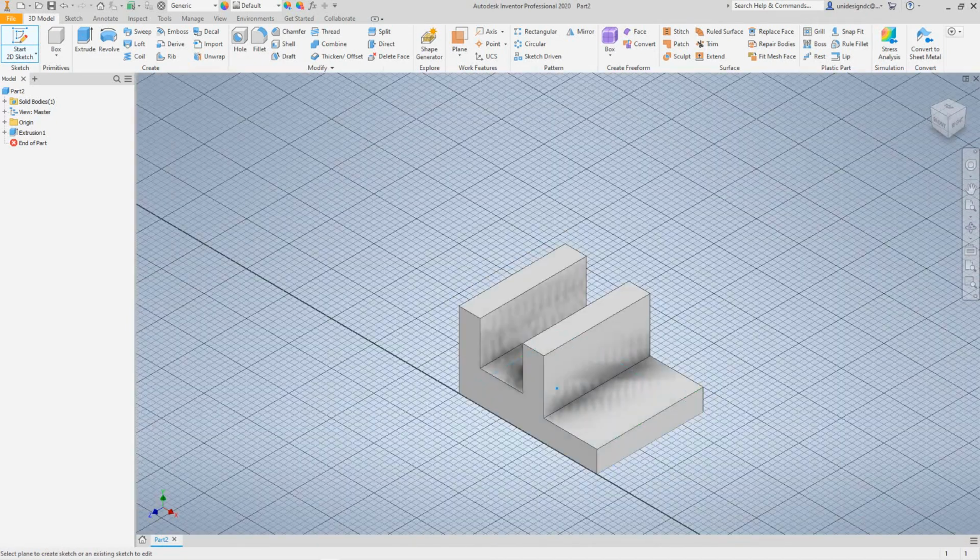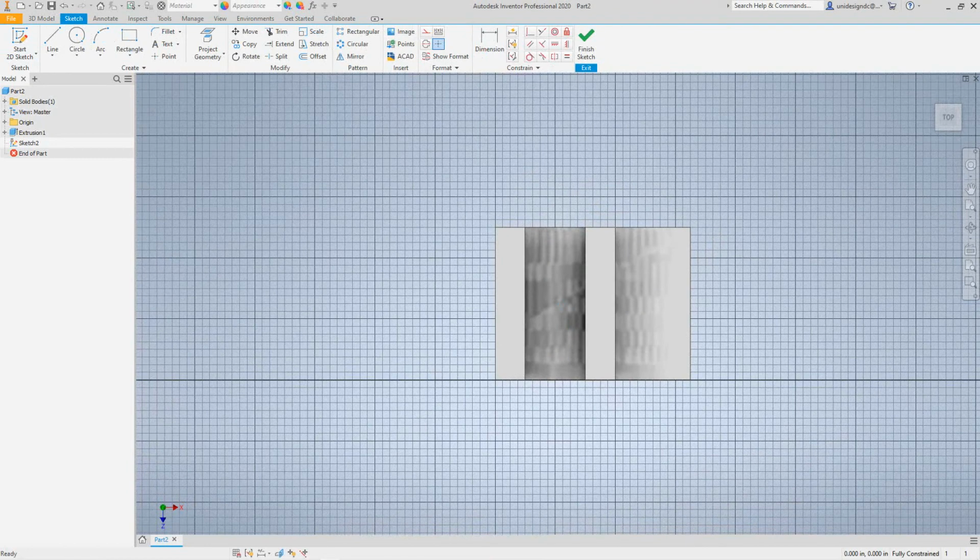So we'll select that bottom face, and then from here we'll create a 2D sketch, and we want to create a circle. So I'm going to just take this back here. I can do it here. So I'm going to circle, and I want to find a center point, and that would be the center. And I'll stretch this right out to the end point.